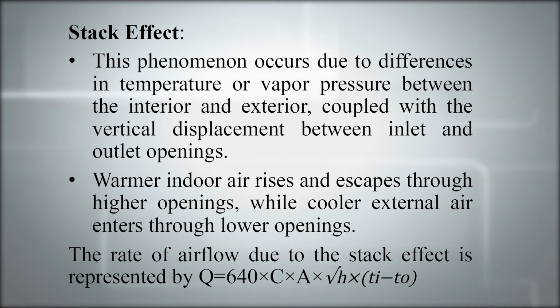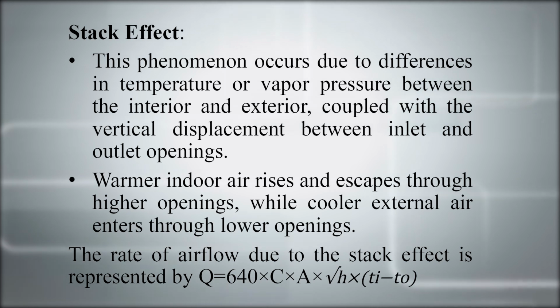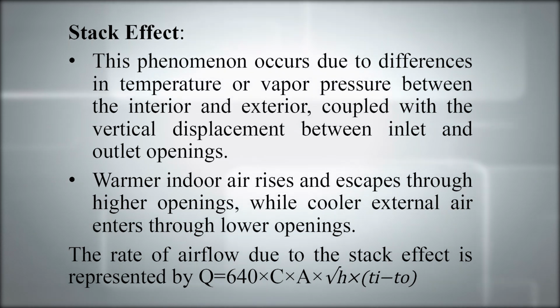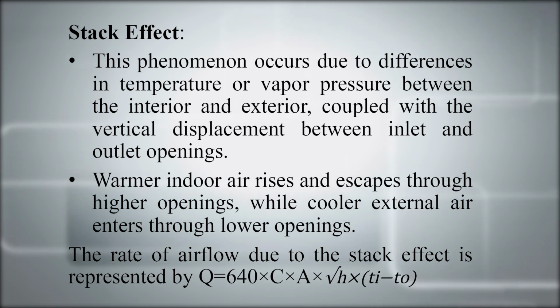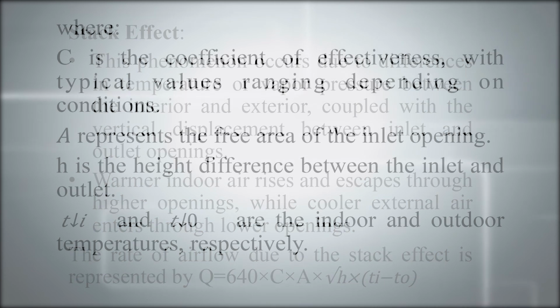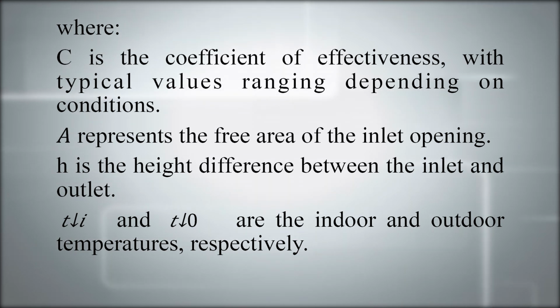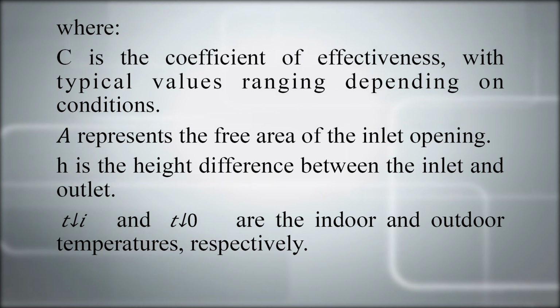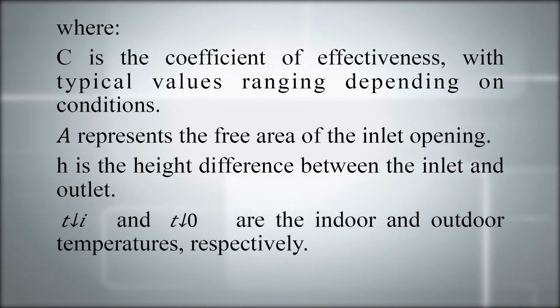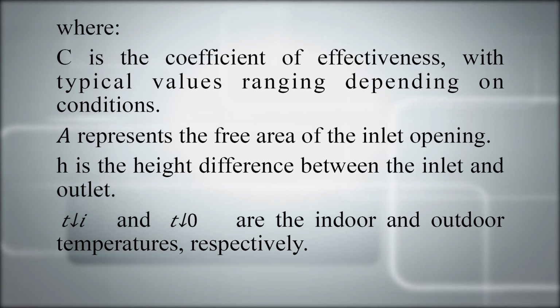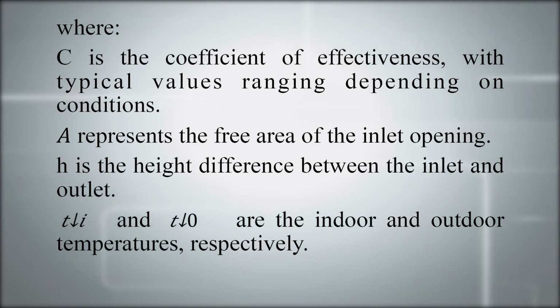The rate of airflow due to the stack effect is represented by Q = 640 C A √(H (Ti − To)), where C is the coefficient of effectiveness with typical values ranging depending on conditions. A represents the free area of the inlet opening, H is the height difference between the inlet and outlet. Ti and To are the indoor and outdoor temperature respectively.